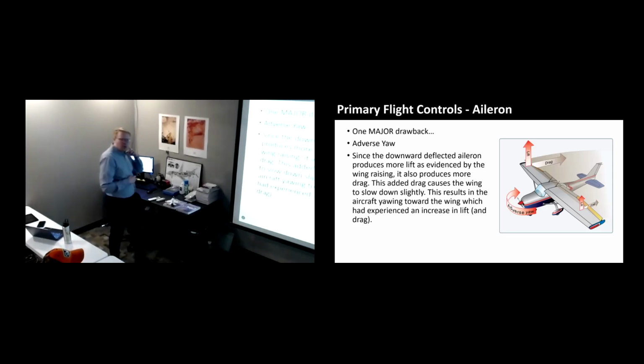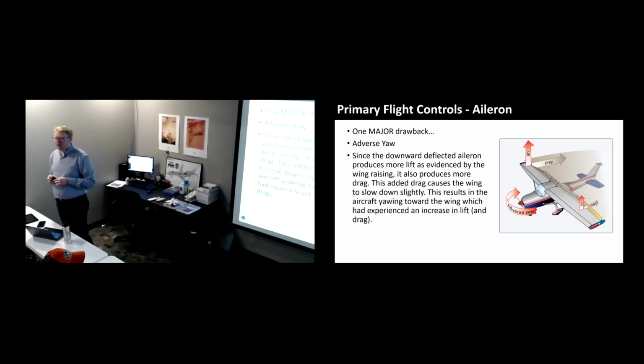Is that not impressive? Our primary thought of aileron is to move around roll, but as soon as you do that, you also induce some yaw. Strange how there are some secondary effects. Good. So would you put in a little bit of left rudder? You would. We're going to talk a ton about rudder. You might have just hit the key consideration here. Why do you think we have a rudder? You kind of just hit it.